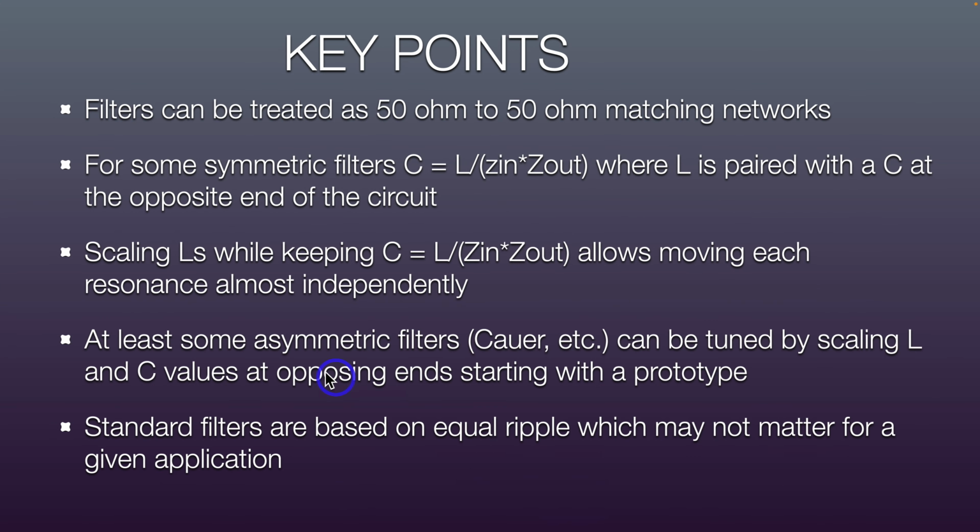Now the key points that I want to go over in this video are that filters to a large extent can be treated as a 50 ohm to 50 ohm matching network. And so a lot of the principles that I worked with in the matching networks then carried over to talking about filters. And what I found out was that for some symmetric filters, keeping the C equal to the L over the Z in times Z out creates a resonance where L is paired with the C at the opposite